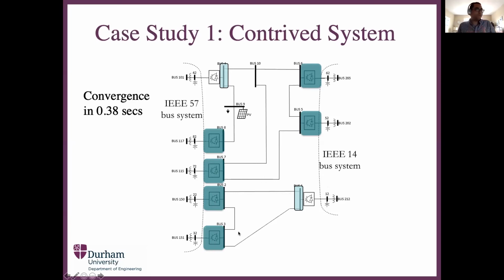So for example, if there is a problem on this side of the interconnector, you no longer see that problem here. You can schedule your response in such a way that does not compromise the stability of these 2 networks. This is something that you don't have in an interconnected mesh AC network.